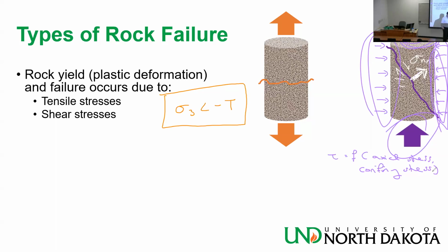If you have, for example, a compression regime, you will have more faults with a 30-degree angle, 45, 30, something like that. If it's an extensional regime, you will have more faults with 60 degrees, which is normal stress. Normal faulting. That's how they do paleostress analysis, when they map everything with faults, what they call brittle deformation in the basin. Even in drilling, the cutting rate of the rock is at these angles.